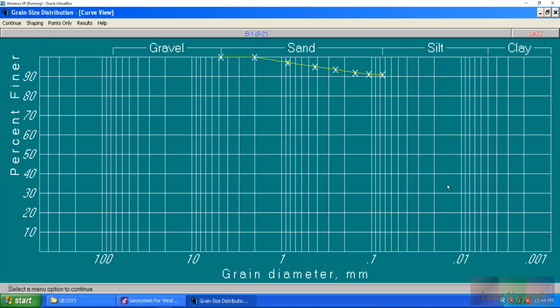So the thing is, silts are more dense than clay. So when you do your hydrometer test, because technically you're going to suspend all your particles before you put your hydrometer in. See, that's some of those parts that I was missing out on before when I was skipping around describing the test. So your silt particles are going to fall faster in your solution than your clay particles. So let's say we're here on the 200 mark, give or take. I think I'm past the 200 mark.